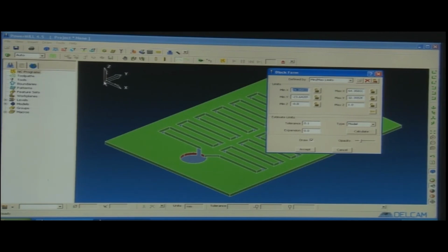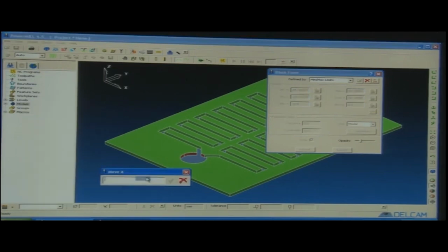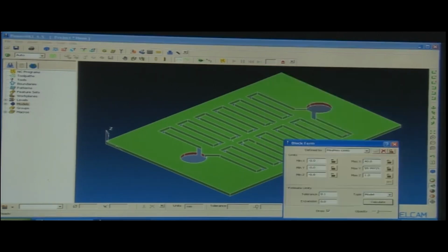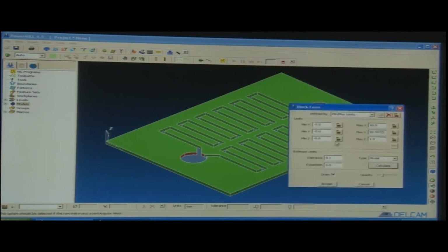See, this is the center of our model. So, this is 0 0. Now, we can see this is 0 0 of our workspace. This is x y z 0 here, and this is the corner of our block. So, we need to match this center here. What we can do is move x to 0, move y to 0, and we have also moved z to 0. Now, x 0, y 0, z 0 makes the origin of the workspace, and the origin of the workspace and the corner are now matched.